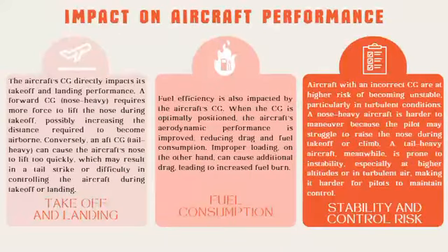Impact on aircraft performance, takeoff and landing. The aircraft CG directly impacts its takeoff and landing performance. A forward CG requires more force to lift the nose during takeoff, possibly increasing the distance required to become airborne. Conversely, an aft CG can cause the aircraft nose to lift too quickly, which may result in a tail strike or difficulty in controlling the aircraft during takeoff or landing.